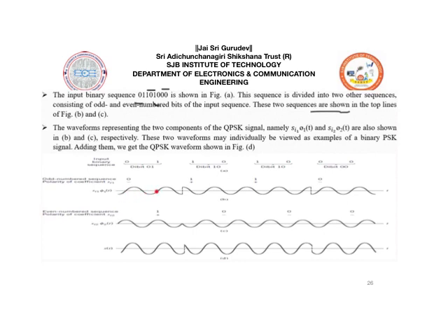After multiplication with the basis function, this is the representation that we get. This is 0. Then 1, there is no phase shift, so it starts at this point. Again 1, there is no phase shift, so it is starting at this point. Next we are taking 0, there is a phase shift, so it has to start in the negative region, having a 180 degree phase shift.